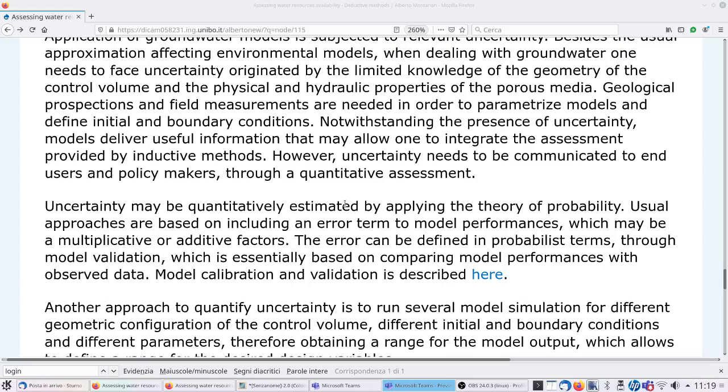Solutions for both the problems are mathematical models which involve parameters. These parameters need to be measured or estimated in some other way. Like for groundwater models, the problem is to quantify specific storage and hydraulic conductivity. We need to refer to measurements, but we can also estimate them. In the same way as we estimated parameters for the iMod model, also parameters for groundwater models can be calibrated. And it's a solution that is frequently practiced and points out that model calibration, so parameter estimation, is a fundamental step of application of these models.